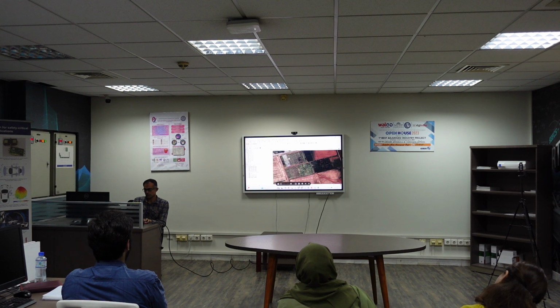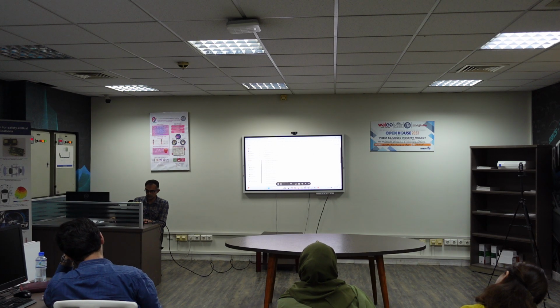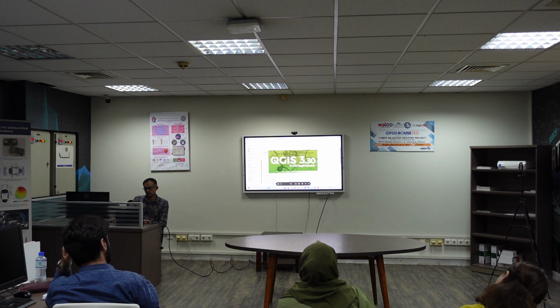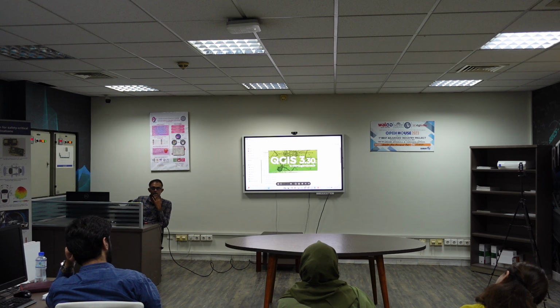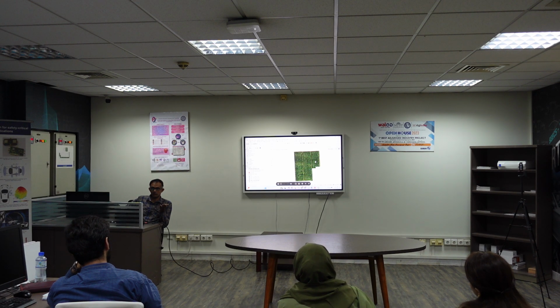Or I could briefly show you another important thing, the way we calculate the height of these crops using the same imagery. We haven't used any radar or something like that. We have just used this. One thing that we have also derived from the photogrammetry processing was the digital surface model, right? The digital surface model basically holds the height information from the surface for each point of that space.